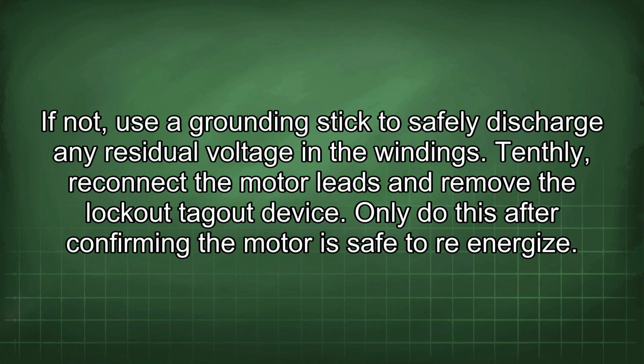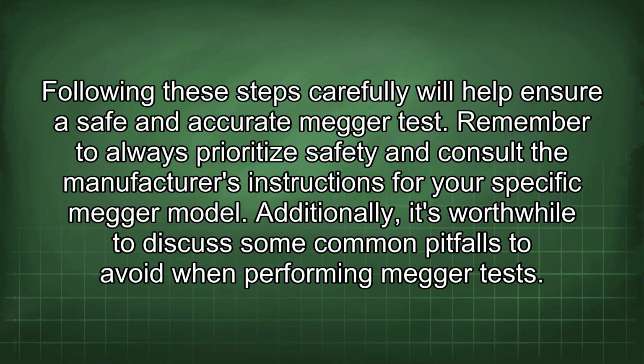Tenthly, reconnect the motor lead and remove the lockout/tagout device. Only do this after confirming the motor is safe to re-energize. Following these steps carefully will help ensure a safe and accurate Megger test. Remember to always prioritize safety and consult the manufacturer's instructions for your specific Megger model.